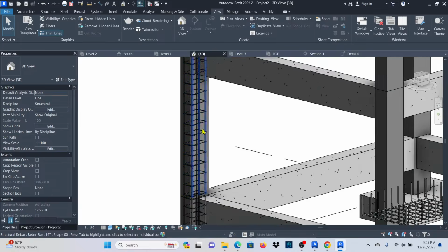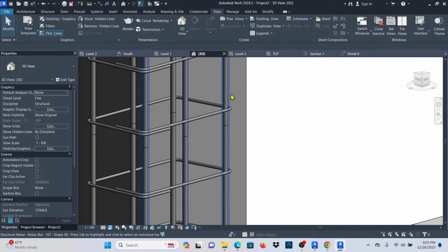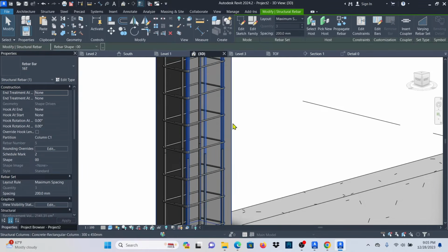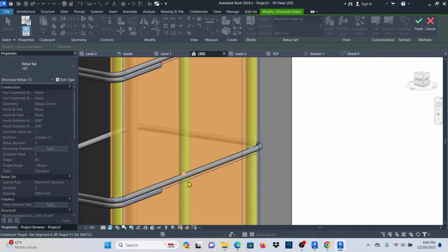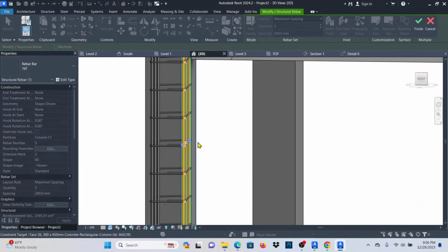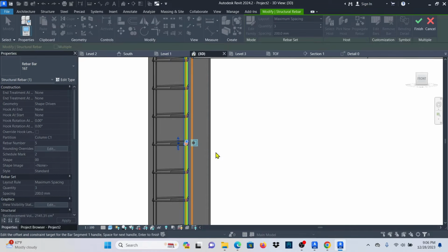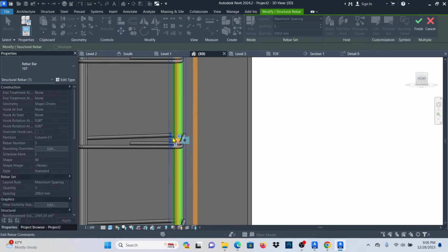First we have this one. Now, I can do the cranking, but let me just try to use some offset so that I can move these bars inside by clicking on edit constraints. I'll select on it. Once I pick that one, let me pick the face of this one. Okay, perfect. So I have two, as you can see, these are parallel planes, this one and this one.